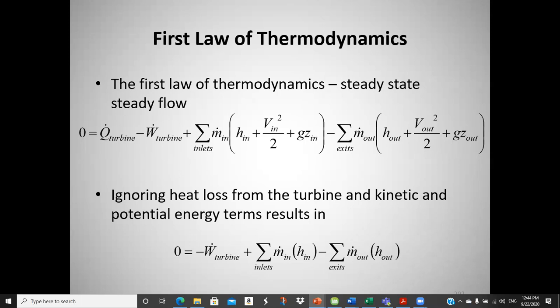The energy passes through this turbine so fast that the heat transfer is insignificant. They put insulating blankets on them anyway, mostly I think for personnel protection, because that steam is probably in that turbine for so many tenths of a second. It doesn't have time to lose much heat compared to the amount of energy that's flowing through there.